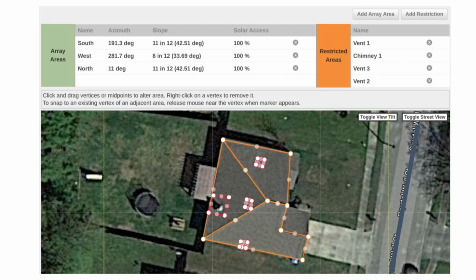At any rate, the clearance areas around a chimney, around a plumbing vent, or around a roof cap can become walkways, and they might need to be repaired at some point in the future. So it's best to allow for some clearance around these obstacles, even when the clearance is not required.